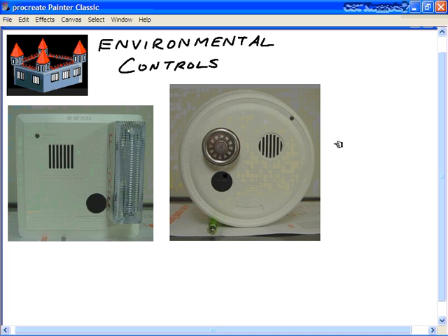Don't forget smoke detectors and fire alarms. These are a couple of high-end fire alarms and smoke detectors also placed strategically throughout their organization. They should have an audible alarm linked to a monitored guard station. You should have smoke detectors and fire detectors above and below the ceiling tiles and below the raised computer room floor.